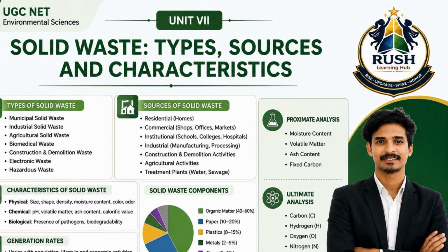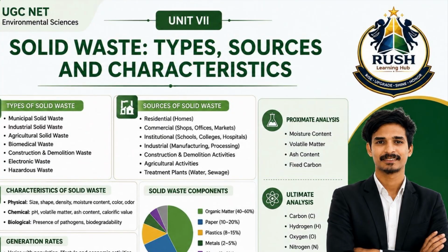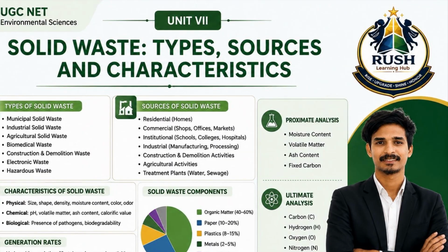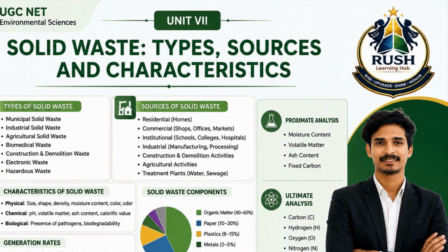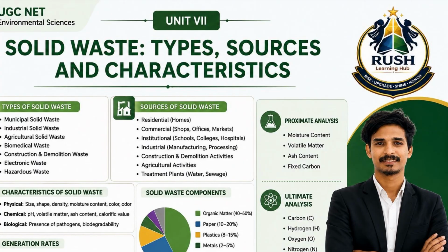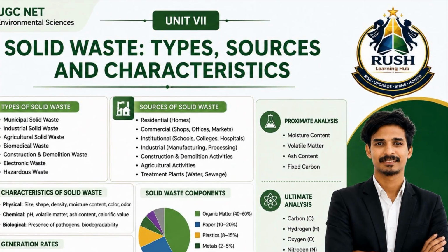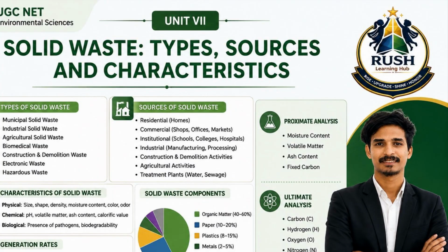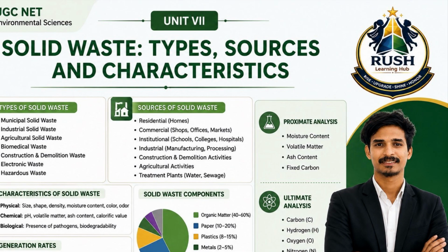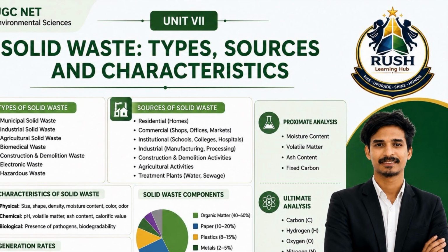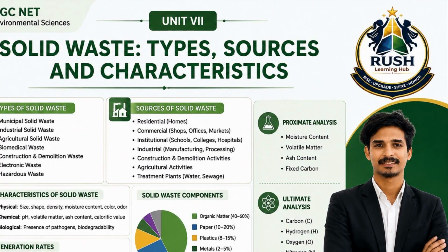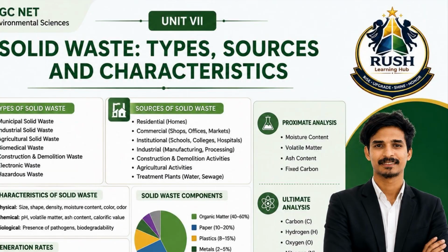Now let us understand another important concept, the generation rate of solid waste. Generation rate refers to the amount of waste produced by an individual per day. It is usually expressed in kilograms per capita per day. Waste generation depends on population size, economic development, lifestyle, urbanization, and consumption patterns. Developed countries generally produce more waste per person than developing countries. In India, municipal solid waste contains a higher proportion of biodegradable organic matter compared to many developed nations.